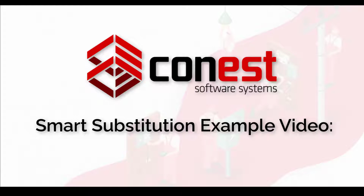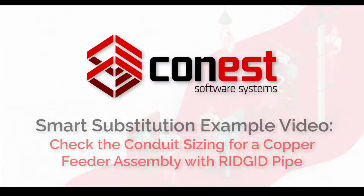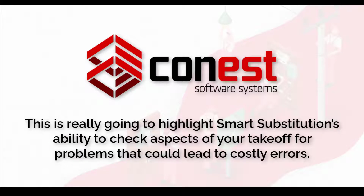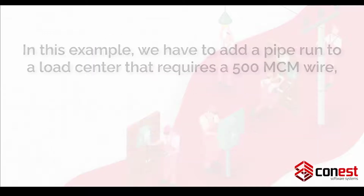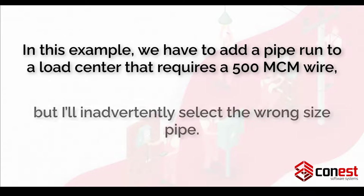Today we're going to use this optional feature for IntelliBid to check the conduit sizing for a copper feeder assembly with rigid pipe. This is really going to highlight Smart Substitution's ability to check aspects of your takeoff for problems that could lead to costly errors. In this example, we have to add a pipe run to a load center that requires a 500 MCM wire, but I'll inadvertently select the wrong size pipe.